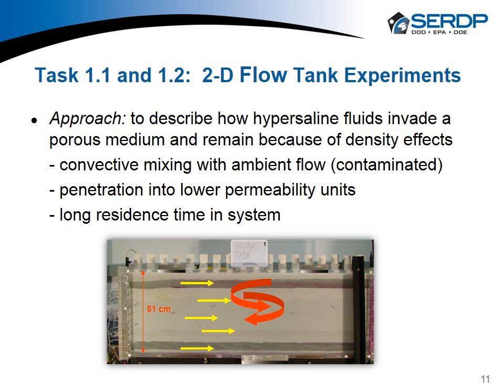So in other words, what those little red arrows on the flow tank show you is the idea that if we put a dense fluid in that upper unit, the thin clear unit there, the density will cause the potassium permanganate to move deeper down into the flow system, gradually mixing and so on. And if that deeper unit at the very bottom of the tank was contaminated, then this potassium permanganate we put in the system would slowly bleed in there over a longer period of time.